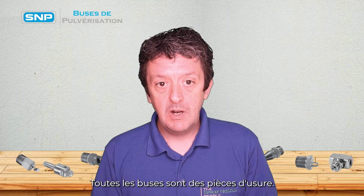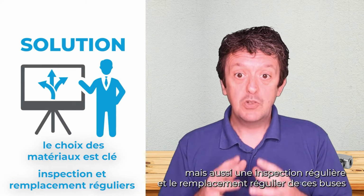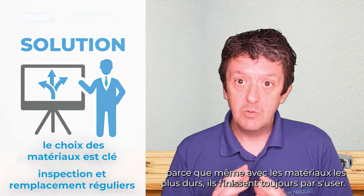All nozzles are a wear part. So the real solution to this is not only to select the correct material, but also regular inspection and regular replacement of those nozzles, because even with the hardest materials, they're still going to wear eventually.